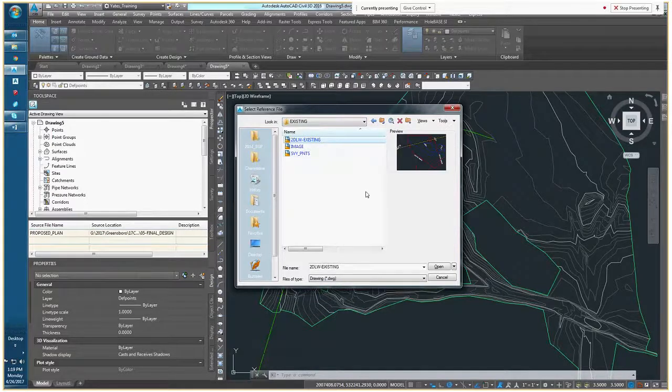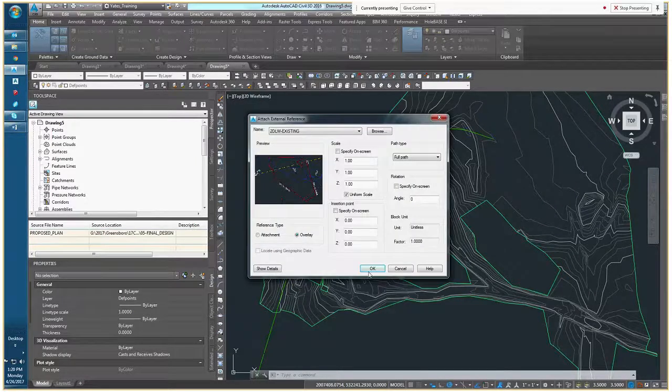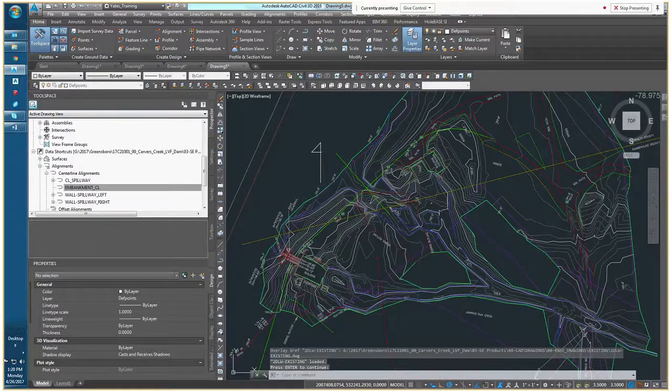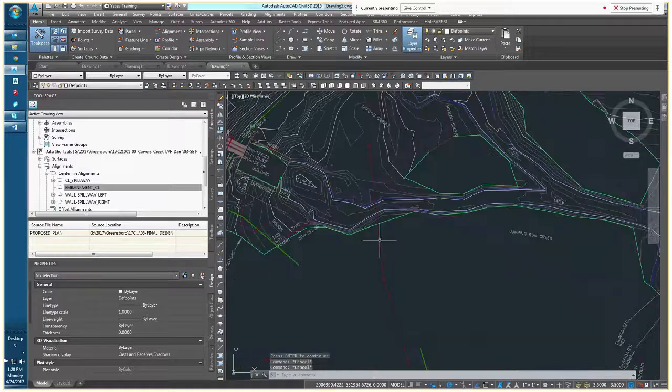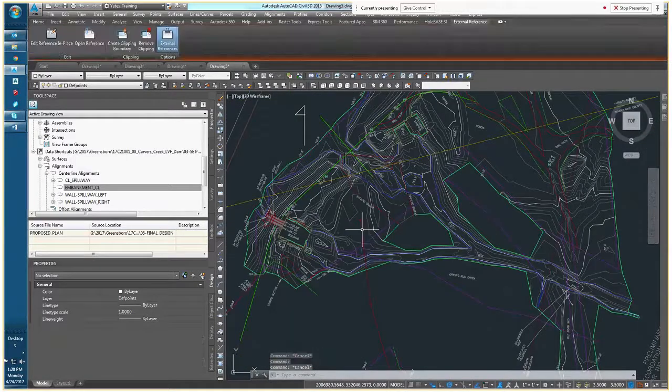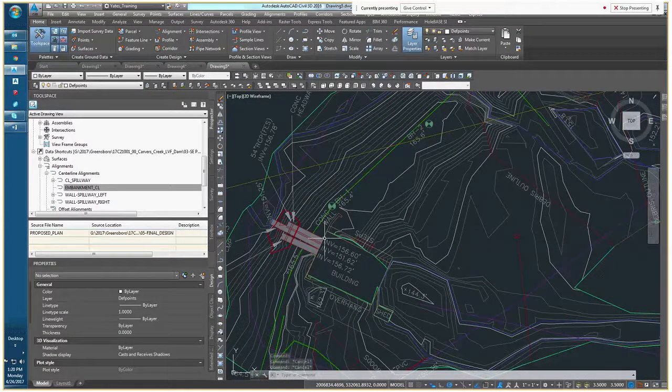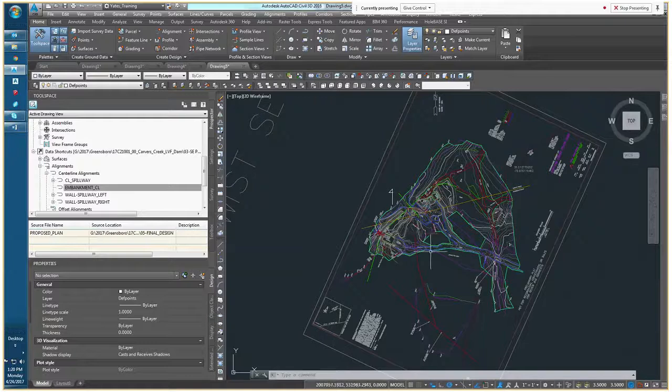All right. We have a 2D line work existing XREF based on the detailed DWG template. Again, using the overlay and the defaults of scale by 1, an insertion of 0, 0 with a rotation of 0, and we'll bring in that XREF. Okay. All of this line work, everything here, the text even, all of the pipes that were caught in the field, all of this was gathered by a surveyor. And if we were to scale this for any reason at all, we're literally playing God with this drawing. And it is just a recipe for disaster if it's not done carefully.